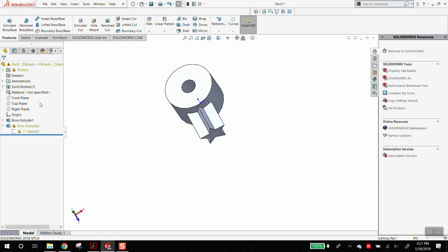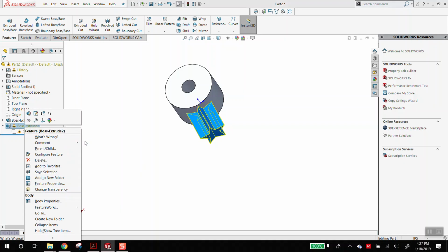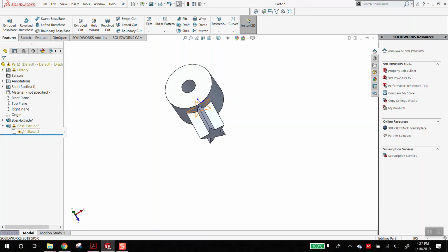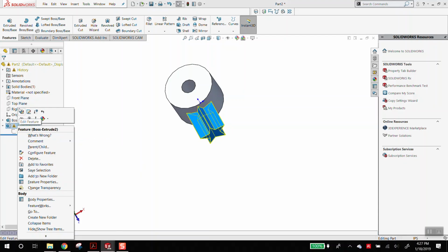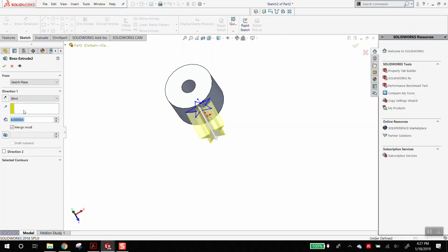They are still one object, which again, I'm impressed that the program figured that out. I'll be honest, I did not expect that. But yeah. Let's mess with that. So, if we just build off of this, if I go here and right click, so the plane is missing, or here, let's just right click, edit the feature. If I uncheck merge result and just click check.